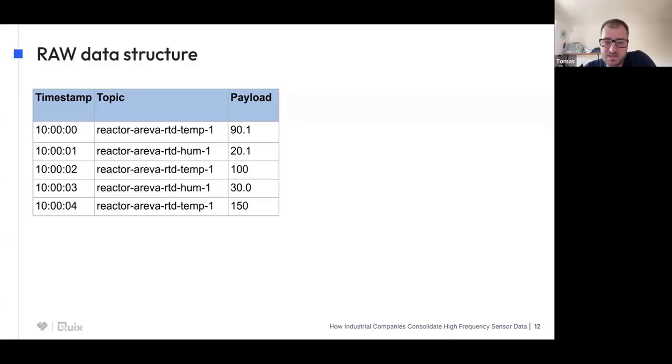If it's a more complex situation, you can have, for example, a room slash machine slash module slash sensor. And then in the payload, you would see the number representing the value of the sensor, or a binary if it's something more complicated. This is how MQTT delivers data.